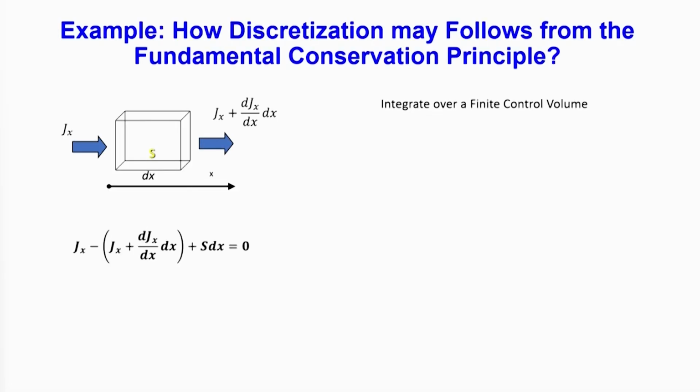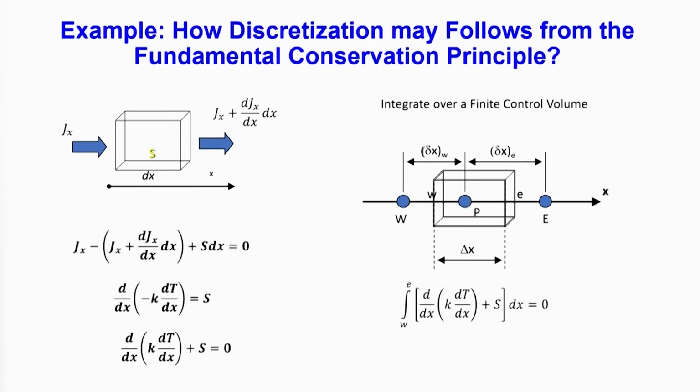So, we will discuss the finite volume method, not just because you will do your practical work in this course using that, but also because it follows from the fundamental conservation principle. We talked about the fundamental conservation principle: you have a control volume, something is entering and something is leaving, and you write a balance, that is, in minus out plus generated equals change. Yesterday in the previous session we talked about this.